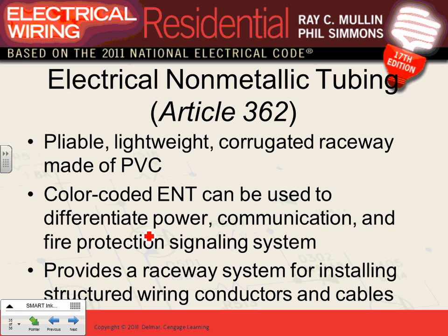Electrical non-metallic tubing. For non-metallic, there's the notoriously famous PVC, and there's also electrical non-metallic tubing. Application is barns. They use a lot of barns because of highly corrosive environment. This is what they call ENT, like the ear, nose, and throat doctor. This one is for highly corrosive environments. It's blue, it's flexible, it's non-metallic.